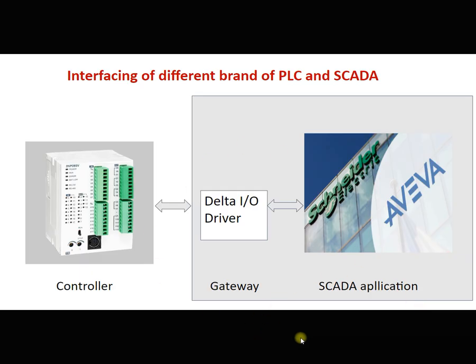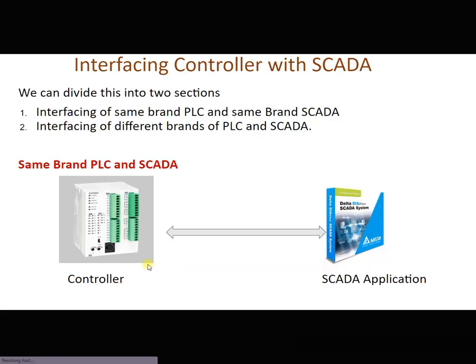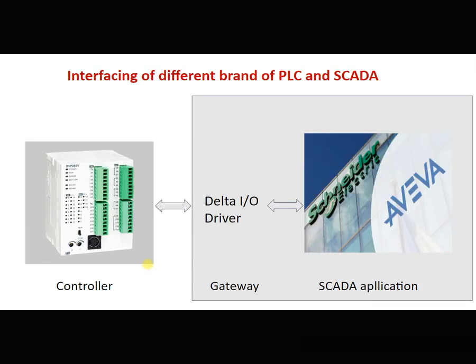Like this, if I want to interface my controller with different brands of SCADA, I need to have a driver here. This is a different topic that you will get to know in a future slide, but you should know these things. If you have the same brand, say Delta PLC controller and Delta SCADA, there is no need for a driver. If you have different brands of controller and SCADA, then you need a driver or a gateway, anything.